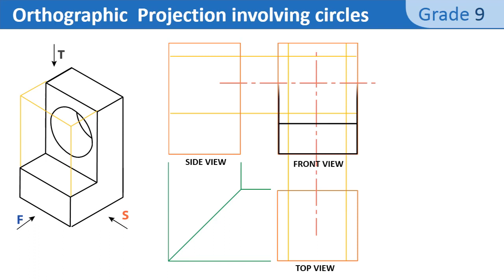So why is the projection line drawn till it reaches the side view and the top view? Because to avoid taking measurement twice. For example, the circle diameter will also appear as hidden details in the side view and top view, and thus it saves time.